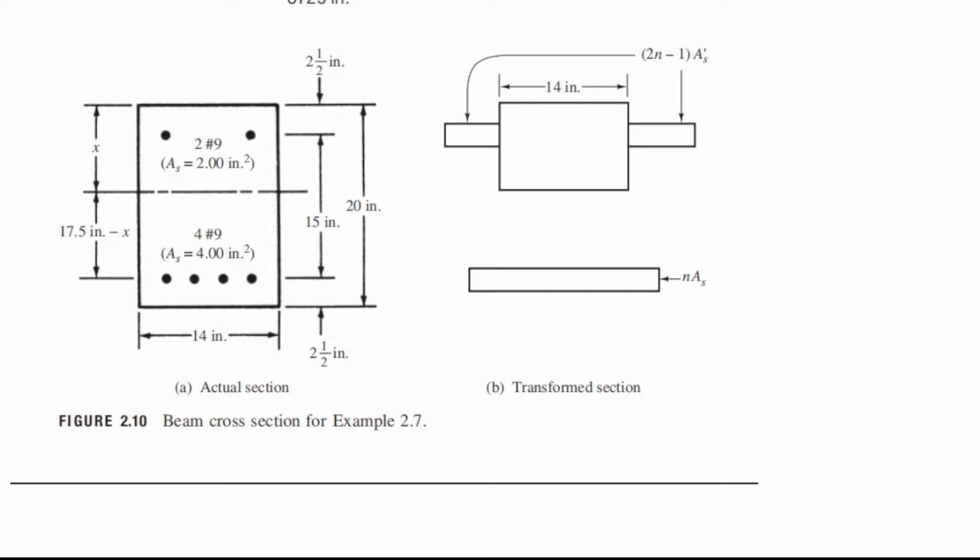These steel bars should yield first before the compressive concrete section is crushed, totally damaged. So this should yield first before this gets crushed. So we are talking about concrete here, and steel bars here.